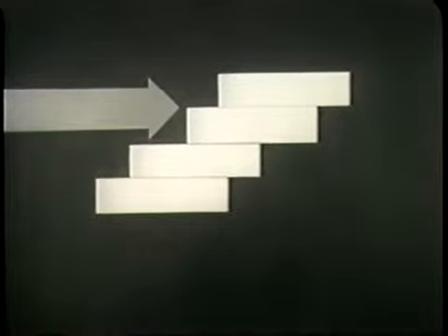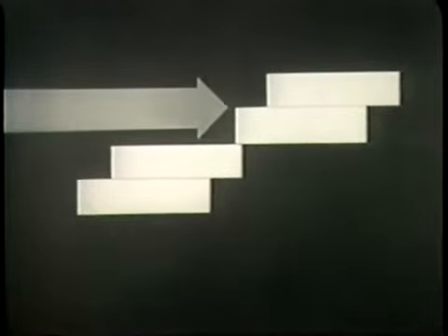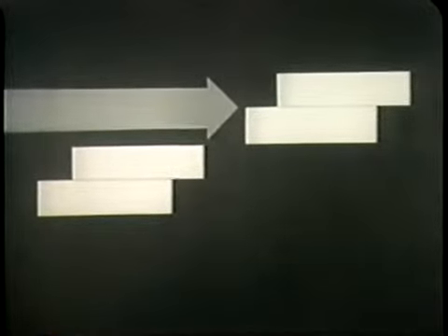Plastic deformation is the basic process underlying the strengthening and hardening of aluminum alloys through cold working. If the force had been increased beyond the metal's ultimate strength, the crystal would have been sheared or ruptured. In sliding over each other in plastic deformation, the crystal blocks rotate, causing the crystal to become elongated.